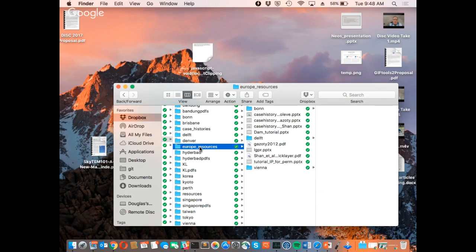the key part of the response, the important information for this correlation between permeability and the IP property, is in SIP, in the high frequency range, let's say 100 hertz and so on. That is because it's related to the fine length scales in the rock, the soils or fine textures, so clay material, silty material. Those small length scales are decisive for the hydraulic behavior, whether the fluid can go through or not. So that is actually the key information.